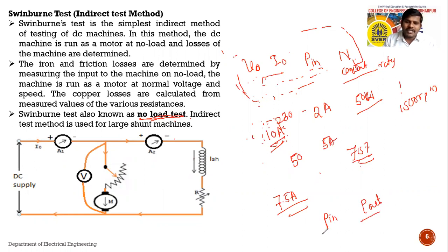At that point we are calculating the input power and the output power, because you people know the losses we have calculated by using the no load reading. Because you people know the supply voltage, and we have assumed the current, suppose the current at this condition is 5 ampere, according to this we are able to calculate the input power.